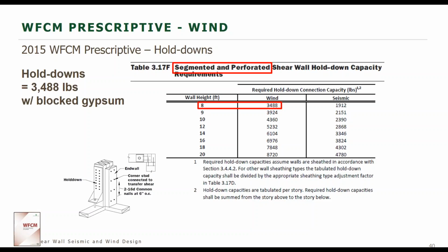So you would need to go to either the screw manufacturer or an evaluation service report from a third party that provides the shear design values for that assembly, the screws and the gypsum. So you can use them in conjunction with our standards, but you'll need to get the design info from somewhere else. Let me qualify that, because I took this question behind the scenes while you guys were teaching.